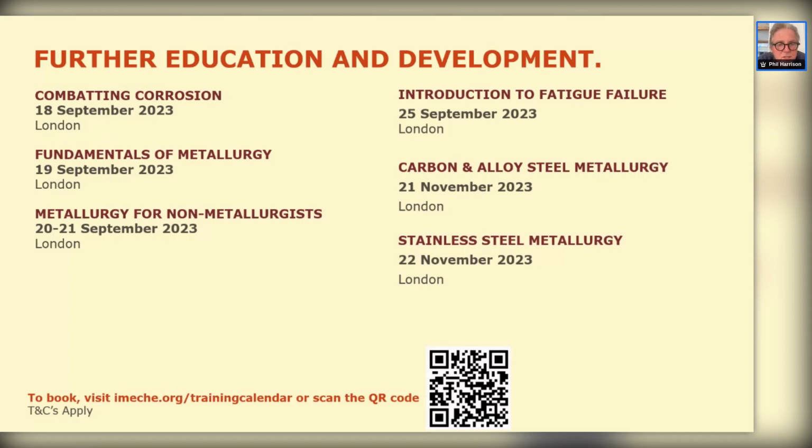Then it led on to things as it's carried on. For example, in the 1930s, car valve springs. It was accidentally found that shot blasting car valve springs, which initially was thought to remove the scale after heat treatment, improved the mechanical properties and life of them. That then was found to be due to the compressive stresses in the surface from the shot blasting.